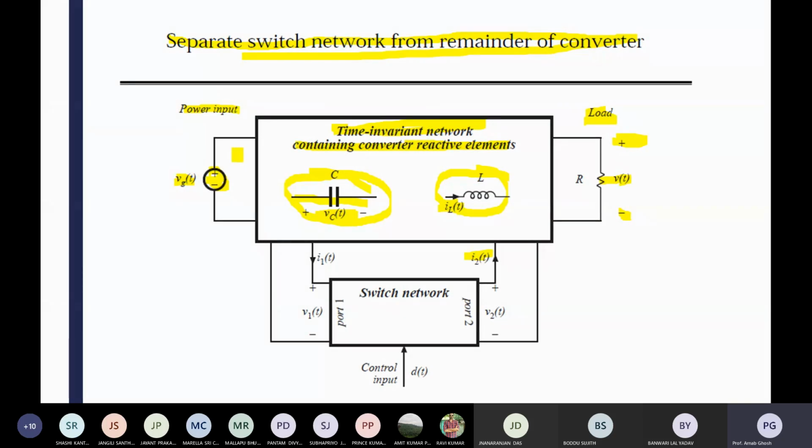That's the basic motivation. Constant voltage and constant current are not the goal; under all conditions, they should take the maximum power. Voltage may be different, current may be different. If voltage is high, current will be low. If current is high, voltage will be low, but power will be constant throughout the path. So in any conditions, any solar irradiation, any change in environment temperature, all the time you should get that maximum power point. That's the basic motivation.